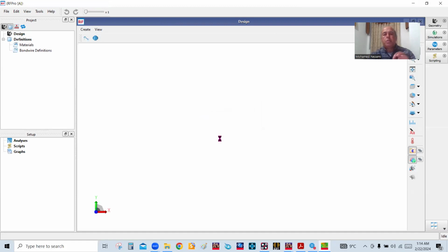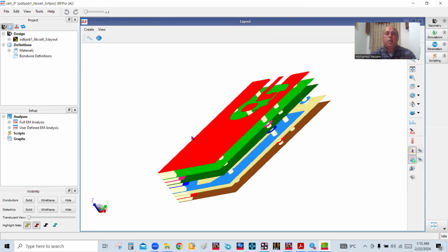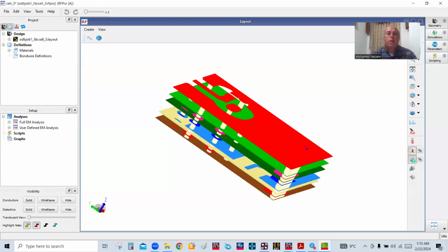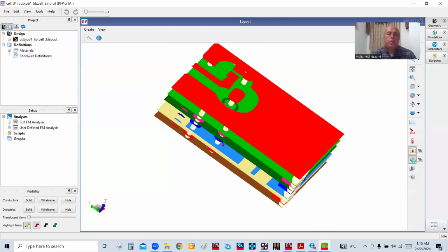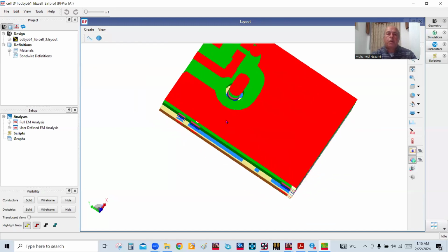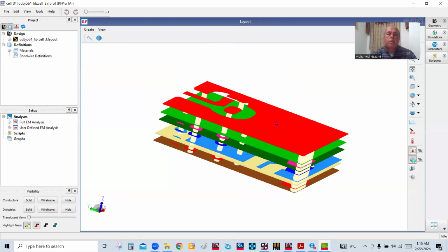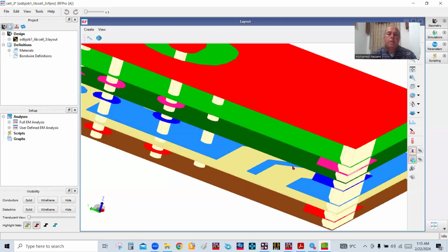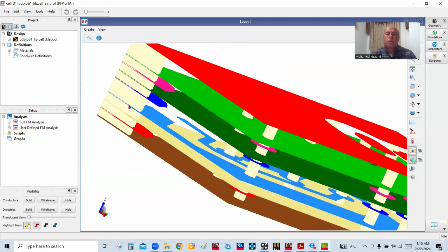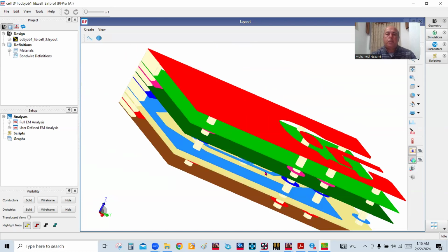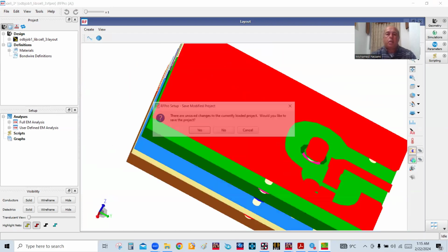And the reason we want to do this is because if there are any big issues, they will show up in the transition. So what we're doing here, we're going to study the impact of going in from the transition from the top layer, the microstrip, to the strip layer. The strip layer in here, that's this trace here. So we could also cut it right to this point here if you want. In fact, we may want to do that as well.